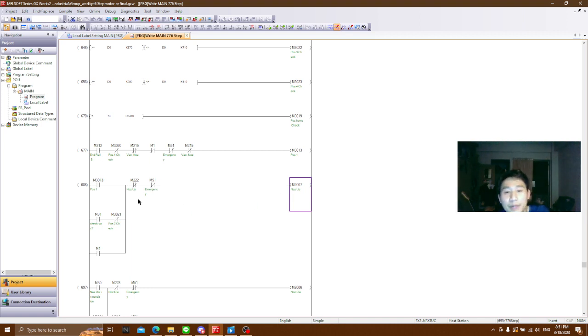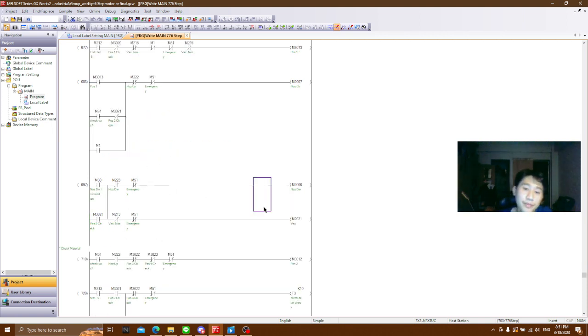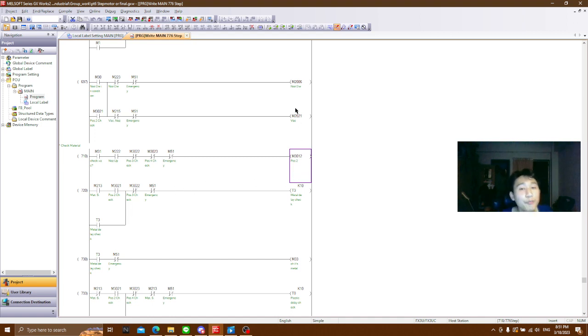the nozzle will go up. If the base position is not position 1, the vacuum nozzle might be down, so we command it to go up, and then go right here, and then down. And after the down conditions are met, it will do whack. It will pull out the workpiece, activate the nozzle up, and then move to position 2, and then work on position 2 again by nozzle down.